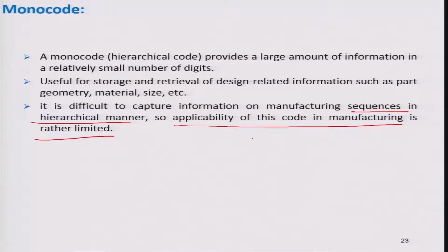Suppose you have a code 3 2 5 6 7, and this code depends on previous machining operations. If you want to make some changes in your part, you will have to change your code also, but since this code is dependent on the previous one, you will have to change your previous machining operation again, so it is very difficult.